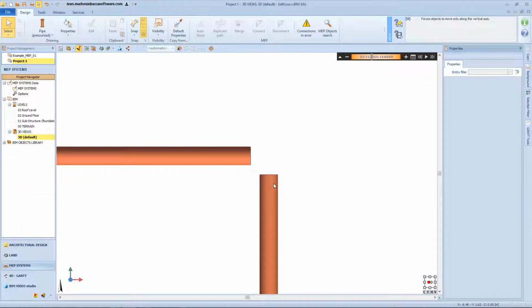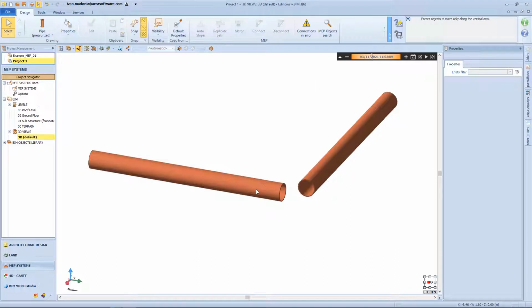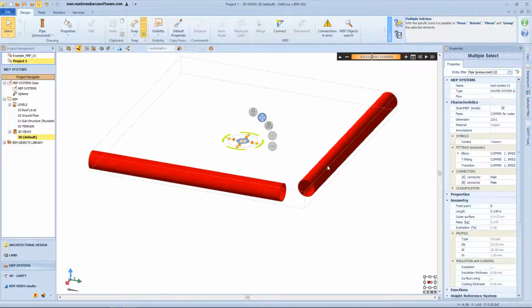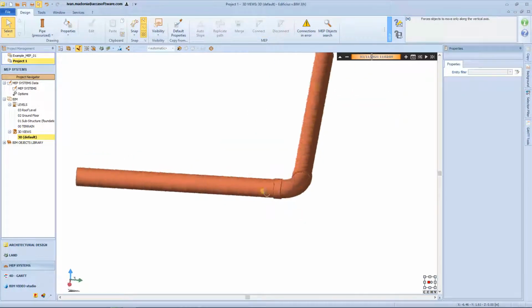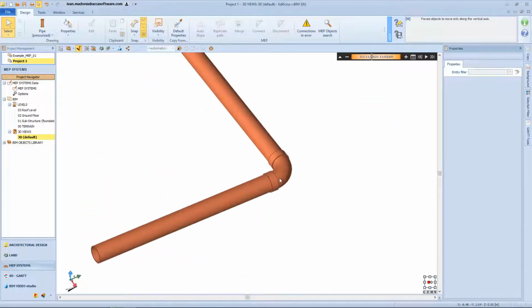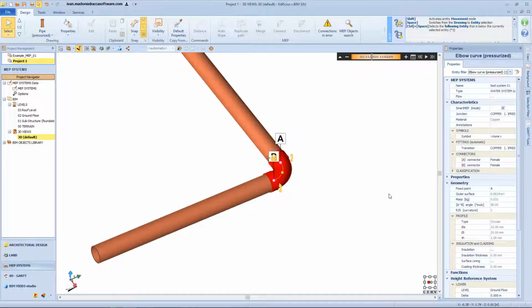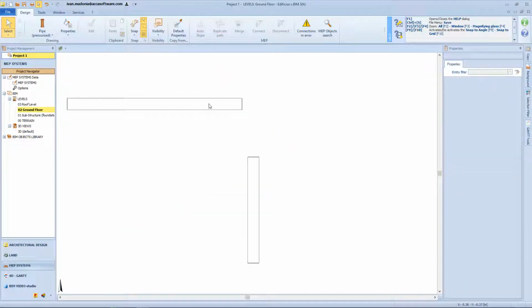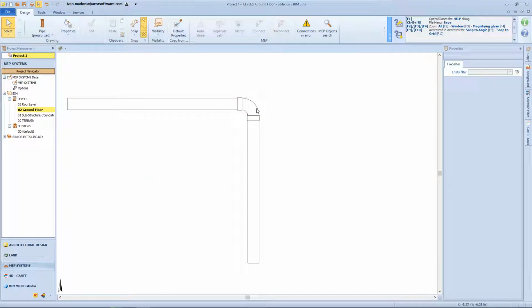If, on the other hand, the pipes to be joined have already been modeled on the drawing and the extensions of the axes intersect, it is possible to create the curve automatically by selecting the two pipes and clicking on the Connect button, which is enabled in the top bar of the drawing menu. In this case, the Smart M.E.P mode must be activated for pipes and curves, which then acquires their parameters and properties. The methods described can be used in both 3D or 2D levels, in this case with the limitations already seen for two-dimensional representations.